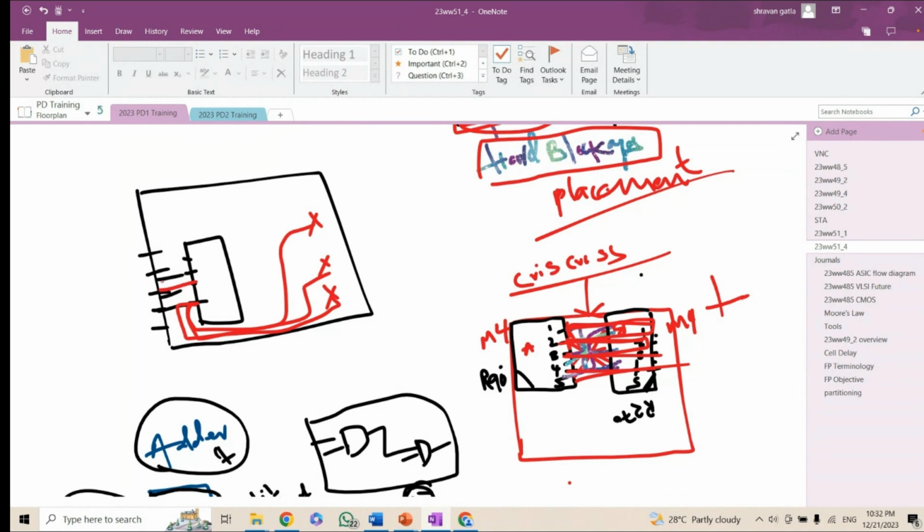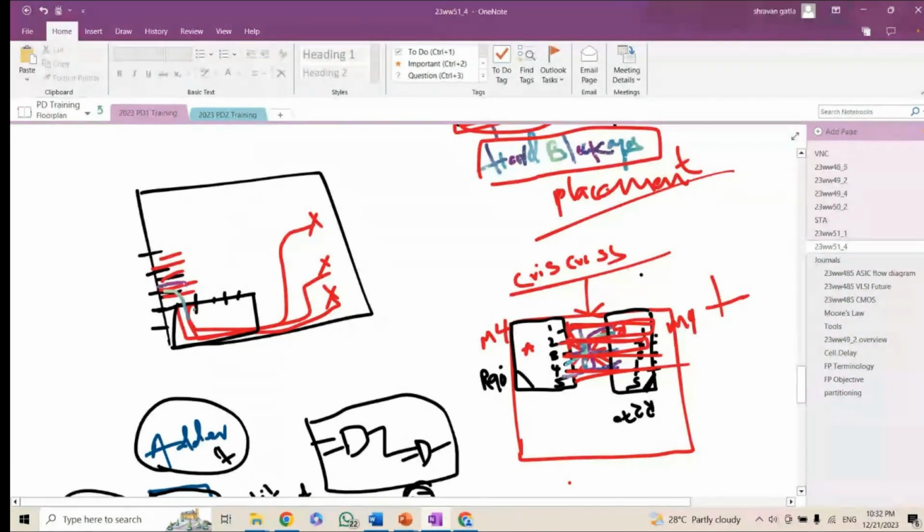But it also communicates with the ports. Yes. Then in this case, what you will do is flip the macro. That is the flip feature we have in our design, in the PD flow. So you can flip it. Then the router finds it easy, right? It just routes like this, and it will just go like this. Right. Suppose we have 10 pins, 3 pins connected to IOs and 7 pins outer. So it's good to place it like this. Yeah. So the main intention of macro placement is that you should avoid the obstructions.